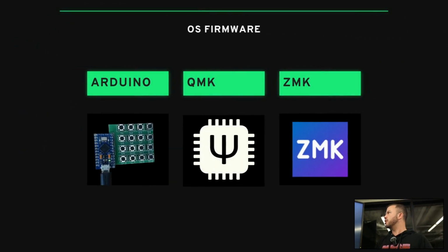And then the other thing you can do is change the firmware. In the very early days, people were just taking Arduinos, writing some C code, and hooking some switches up to them. That's still an option if you want to. People still do hand soldered matrices and spend a lot of time making these things very carefully. But there's one project called QMK, Quantum Mechanical Keyboard, that has taken over as the de facto project. If you are making a keyboard, most people would expect an open source keyboard project to support QMK. It runs on a variety of microcontrollers, from your typical Arduino-like Pro Micros to more recent Raspberry Pi 2040 microcontrollers. They have configuration files that let you set the key map, and let you define where all the keys are laid out if you're building a keyboard from scratch.